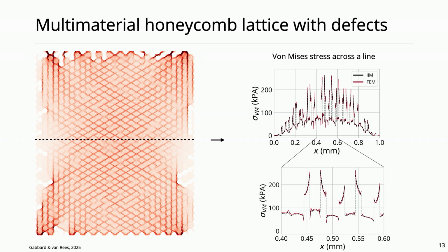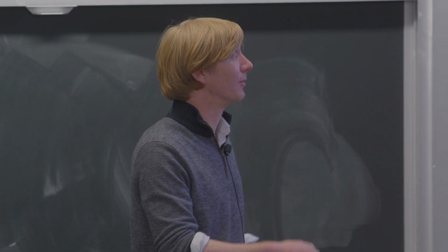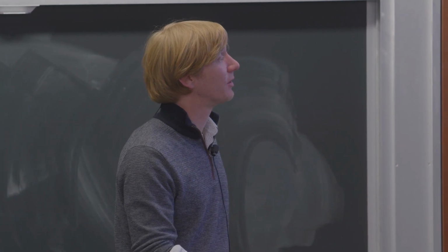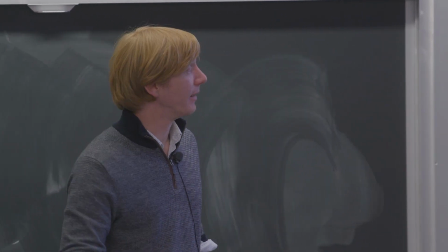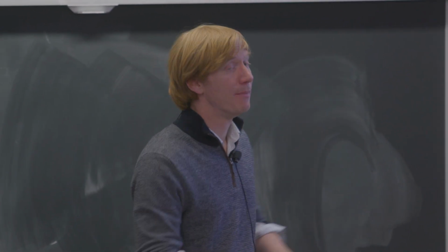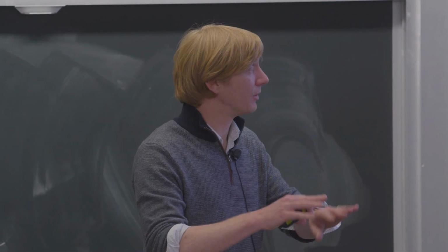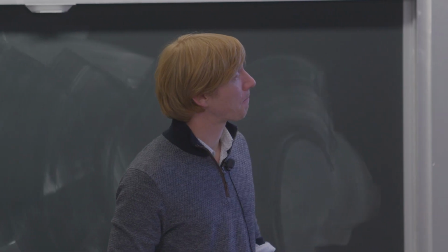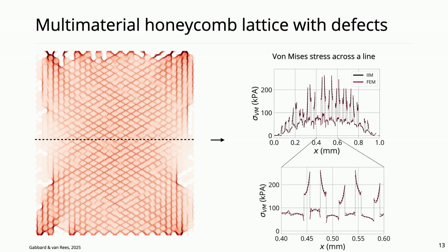We're fourth order accurate in the infinity norm, and we still have sharply resolved jumps whenever we switch from one material to the other, where the black line here is our result, right? So that's the sharp jump. And the embedded finite element method does not resolve the jumps sharply there. So that's immersed methods applied to elasticity.